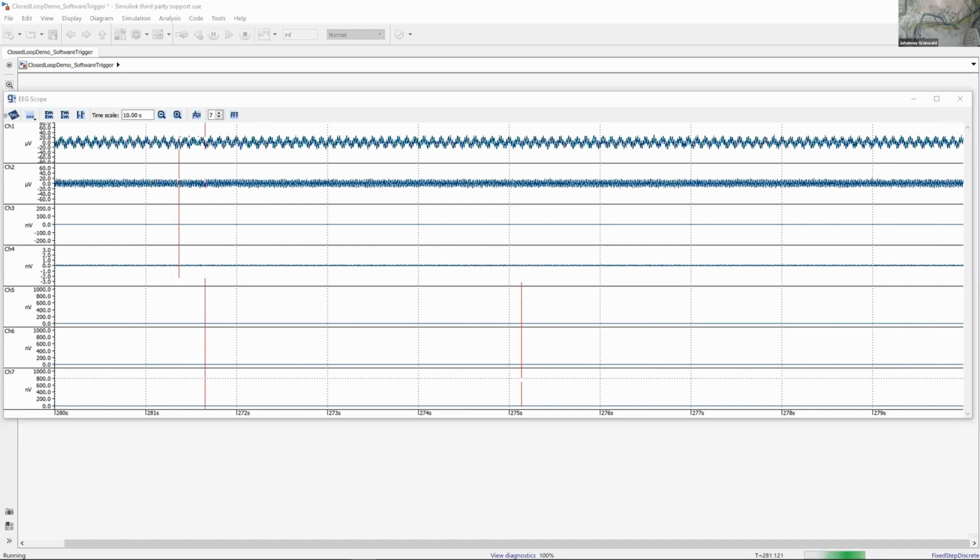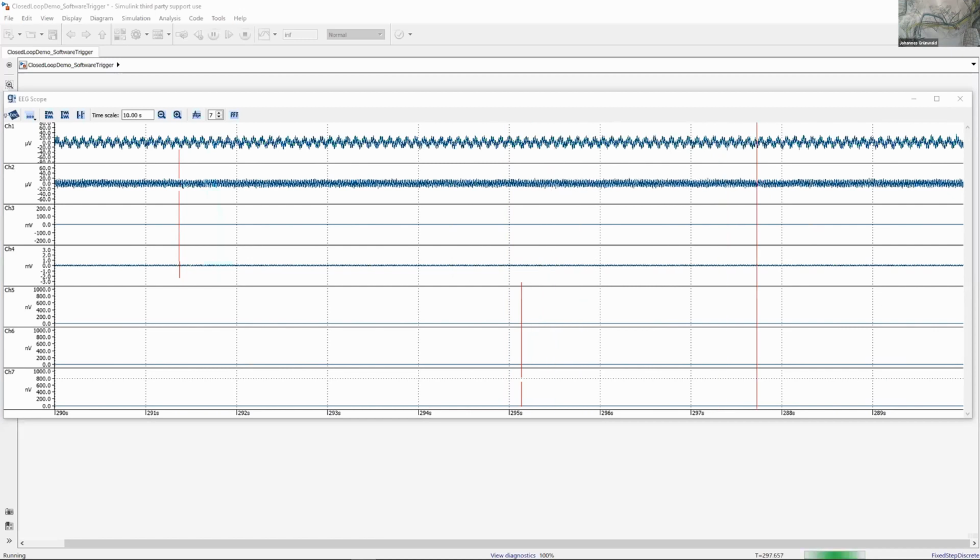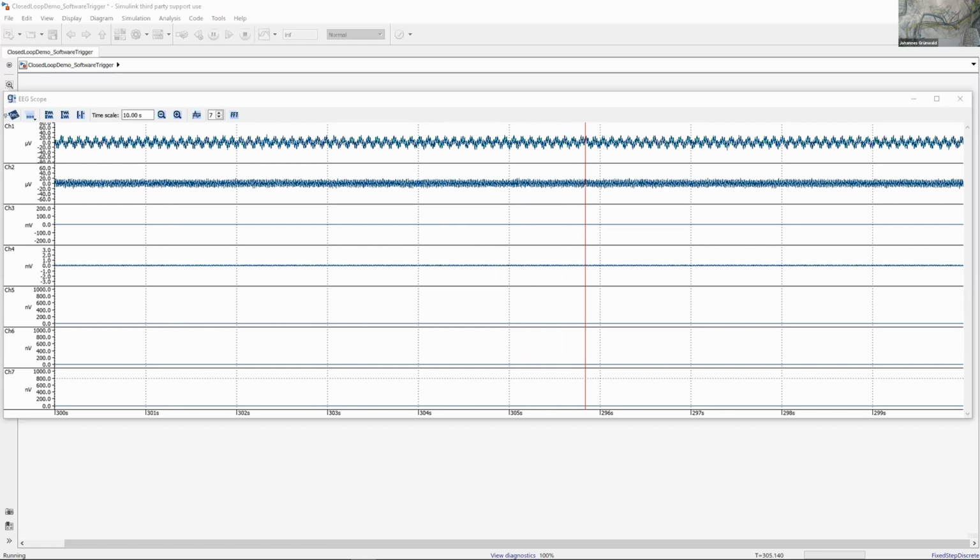So regarding real-time operating system, we all use Windows. As you all know, it's really not dedicated to do real-time operations specifically. Linux would be much better. But on Windows, it's really good to do that. And the minimum latency from a trigger is in the millisecond range, about 2 to 3 milliseconds, and the jitter is very low. But we can give you more detailed answers on that.